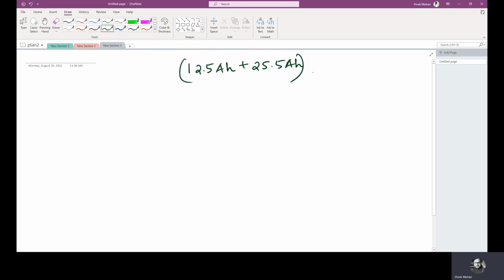And if we know that the system losses are 20%, then I'm taking it into 1.2, which is equal to 45.6 Ah. So this is the total requirement, loads plus losses. Okay, with 20% losses. Now we have to determine the solar irradiation in daily equivalent sun hours.